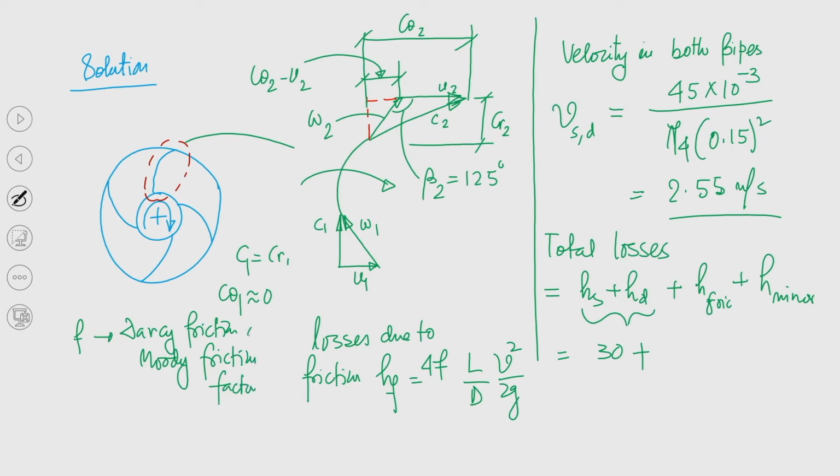Okay. So, you are familiar with this term, and you know this is called Darcy friction factor, but I am telling you this is also known as the Moody friction factor. Rather, I will be using one extra term, say F prime, that is equal to 4 into F. So now I will be considering F prime.